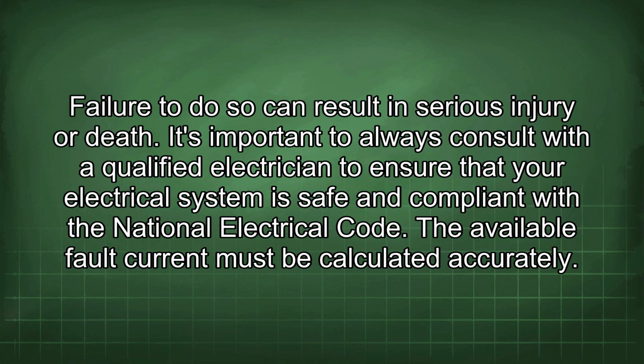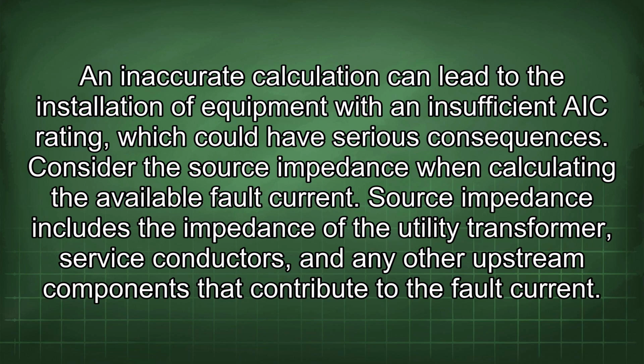It's important to always consult with a qualified electrician to ensure that your electrical system is safe and compliant with the National Electrical Code. The available fault current must be calculated accurately. An inaccurate calculation can lead to the installation of equipment with an insufficient AIC rating, which could have serious consequences.